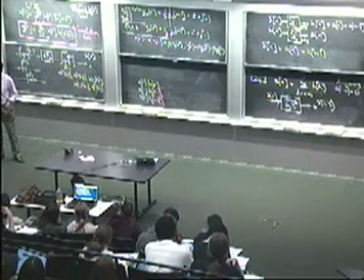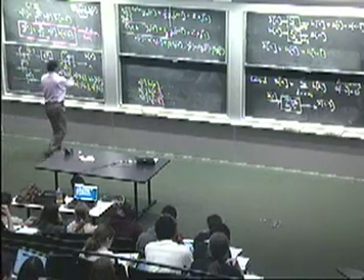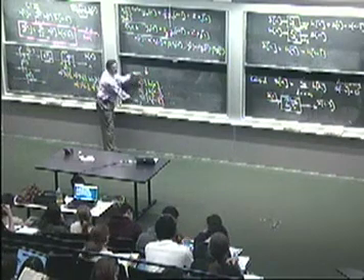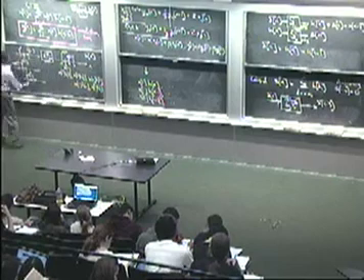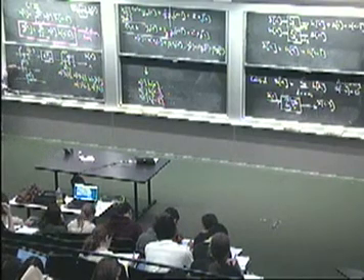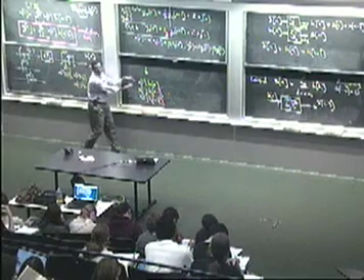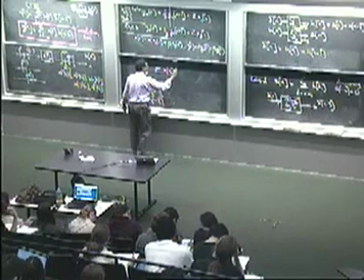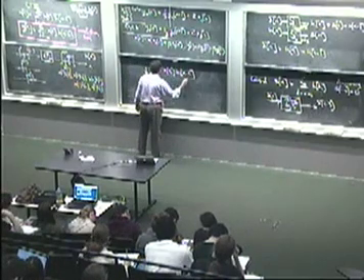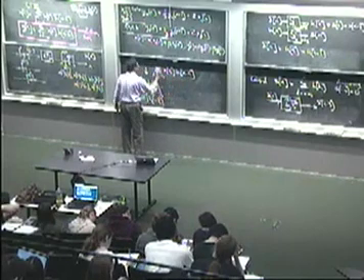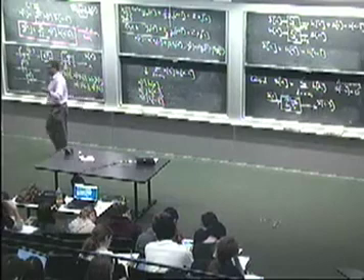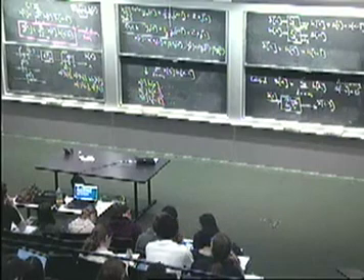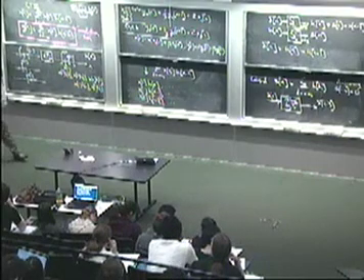And what if you're interested in the value at time n? So you look along here, and you've come to the value at time n. It's going to be the sum of all of these, if your input is the sum of all of these x's, your response is going to be the sum of all of these. So what's the sum of all of these? Well, x[k] h[n minus k]. That's all there is. There's no magic to this. It's just invoking linearity, that's the scaling part of it, and time invariance, which is the delaying part of it. Okay? It's as simple as that.